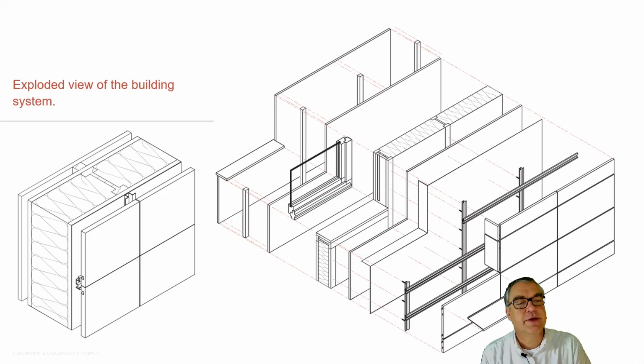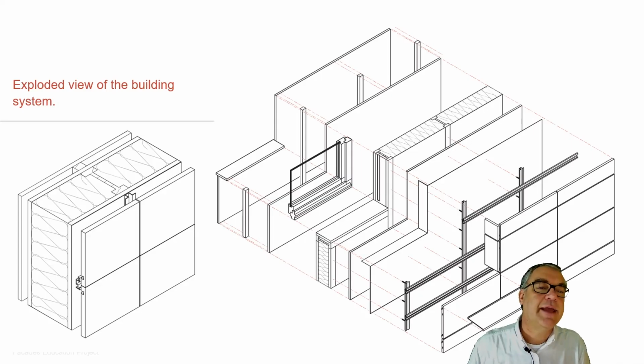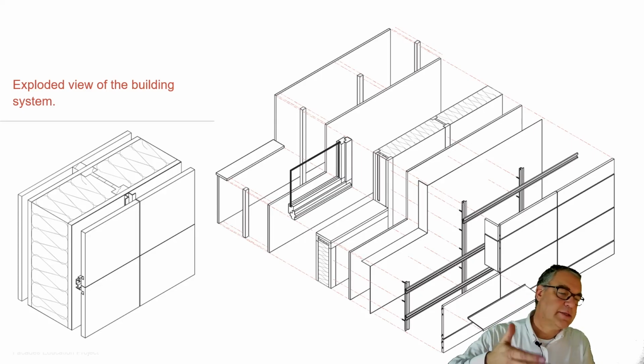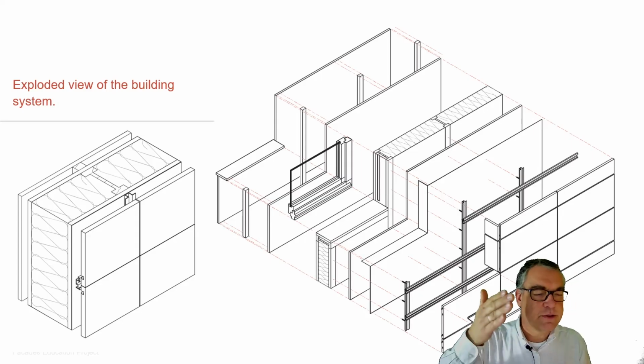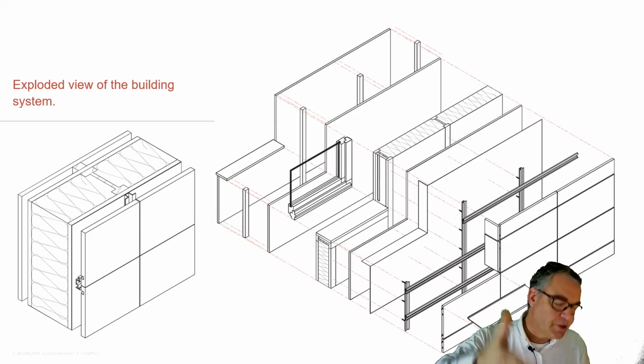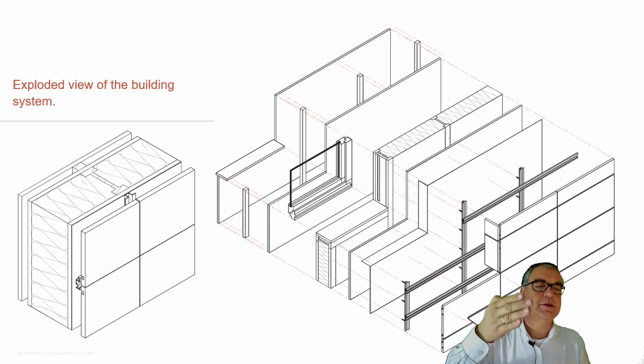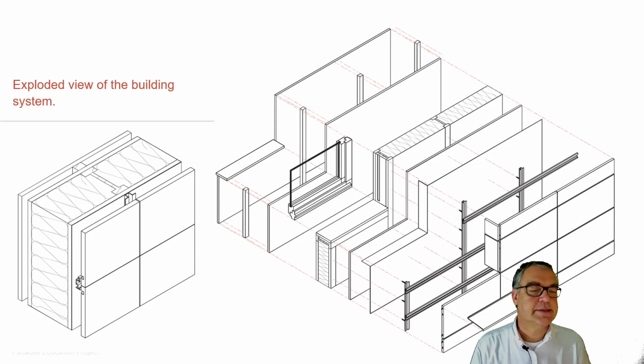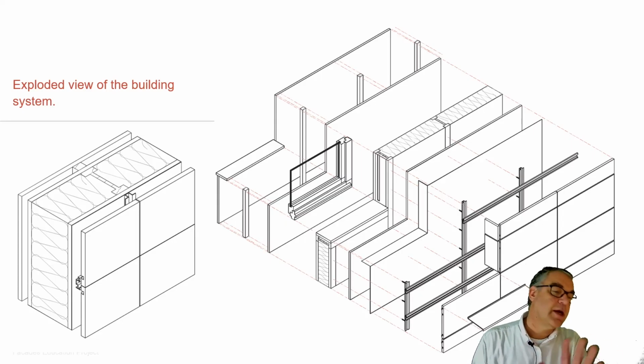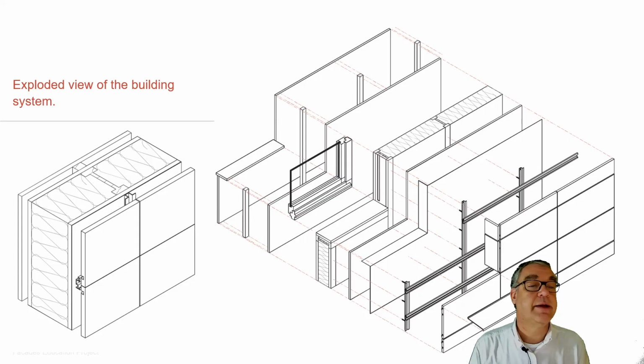We have the main structure, we have the insulation, we have an outer cladding to close this main structure, we have an inner cladding to close this main structure. This inner cladding has to fulfill, next to the structural part, also the functionality of being airtight. As said, inside needs to be airtight. The outer one has to fulfill the structural function, but also being breathable, which means we have an additional layer here to secure that this is not airtight but breathable as a system.